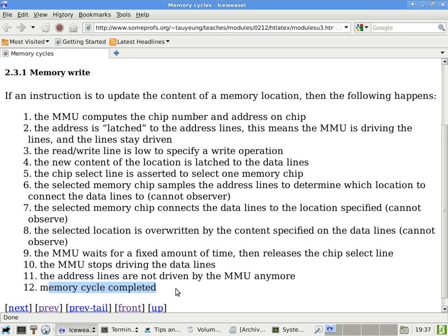The reason why DDR2 and now DDR3 can be so fast is because they can skip a few steps. The memory chips are getting smarter. So what I can do is say, hey, Mr. Memory Chip, I want to start reading at location 88. But I can also tell the memory chip, I'm also interested in the next 8 locations.